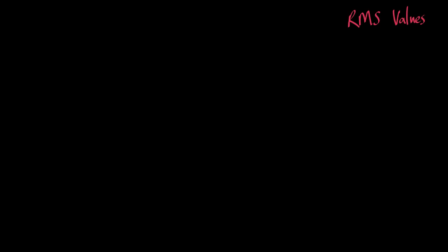Before we continue, we need to get a concept very clear, and that's RMS values of voltage and current signals. RMS stands for root mean squared. Cast your mind back to our discussion about AC versus DC, and you would remember we noted some differences in the waveforms. When it comes to power, we want to be able to compare the effective power despite the difference in waveform, so something like a peak value doesn't help us much at all. Instead, we assign a voltage value based on the average power dissipation in a resistive load.